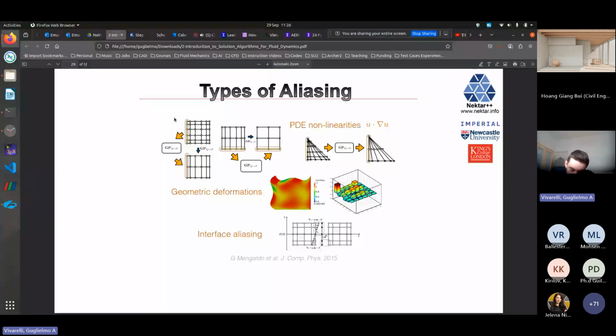So you then move on to a second type with the geometric deformations or negative elements. In high order formulations, you want to capture the curvature of the geometry because you're using a coarse mesh, so you can capture the CAD exactly. The problem is that you're going to end up coarsening the mesh too much sometimes, and this is going to create negative Jacobians. You remember when Mosen explained the mapping from the physical domain to the elemental domain and backwards, you needed to determine a Jacobian. If you've got far-field elements, it's going to be a linear equation, but for the curved surfaces, you now need to introduce this curvature as well. So you can get negative elements and therefore your solver will not run.